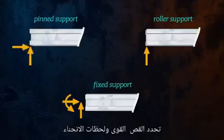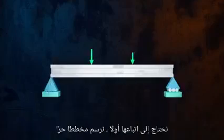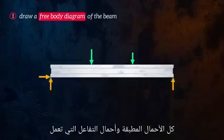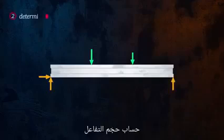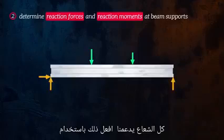So how do you determine the shear forces and bending moments within a beam? There are three main steps we need to follow. First, we draw a free body diagram of the beam. This shows all of the applied and reaction loads acting on the beam. The next step is to calculate the magnitude of the reaction forces and reaction moments at all of the beam supports.